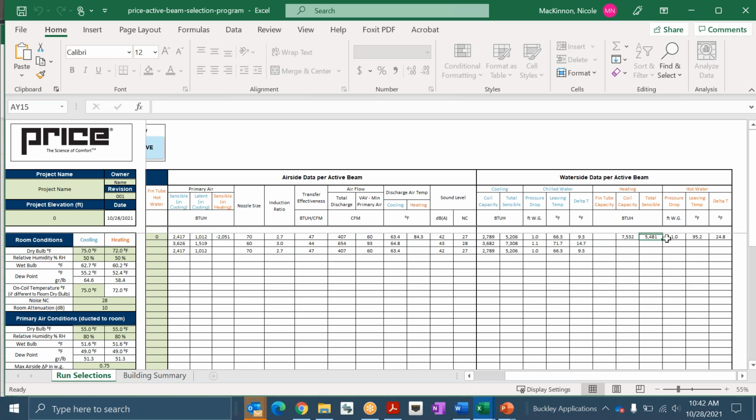What we want to see is the impact of the chill beam on the space and not the individual components of the beam. This is the more important item to schedule, in my opinion. Then lastly, here we got your living air temps 95, a little bit high. We like to be within 15 degrees of your set point, so 90 is usually a cutoff. But we do see higher pretty often with no major issues, but that's one thing to keep in mind. You don't want to stratify that hot air if you're mounted from the ceiling.